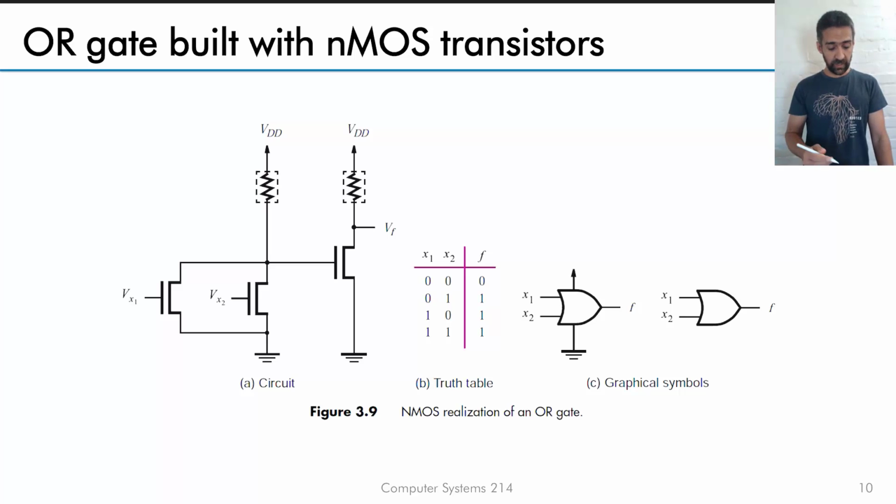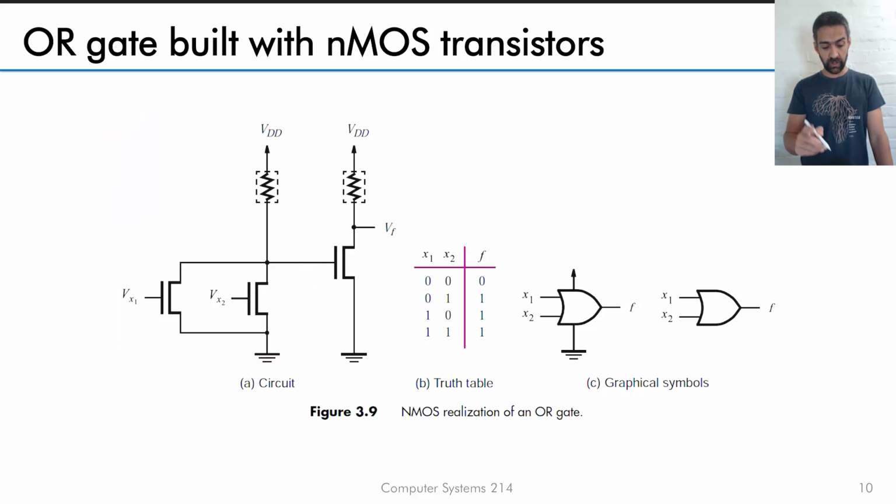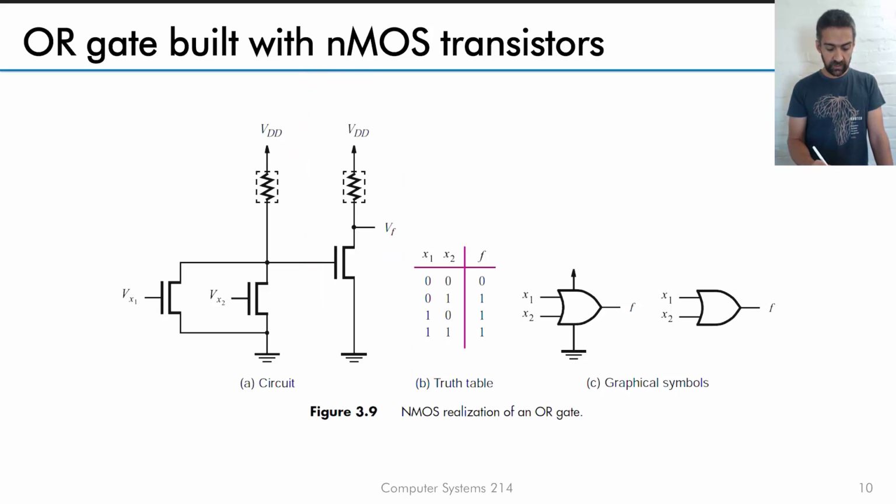So considering what we have on the screen here, on the left-hand side looks exactly the same as what we've just had with the NOR gate. Two inputs, as you can see, two inputs, and then the resistor here that acts as a pull-up in case there's no current flowing, a pull-up resistor. Now what we do is we slap a NOT gate onto the back of it, and as you can see here, this here provides high impedance, so it doesn't really matter that there is a path for the current to flow.